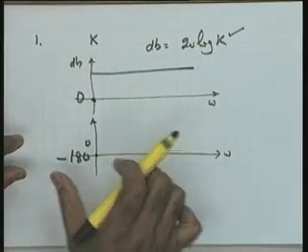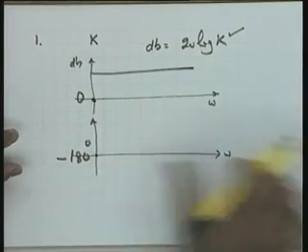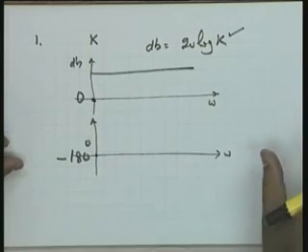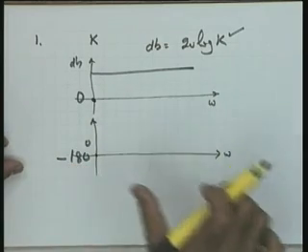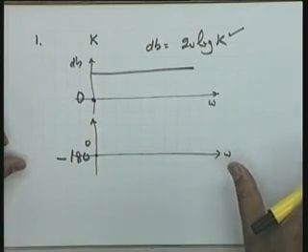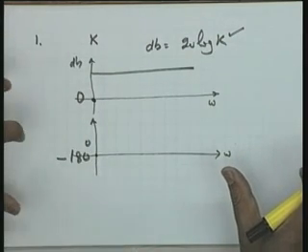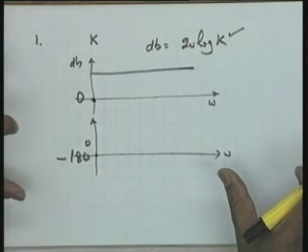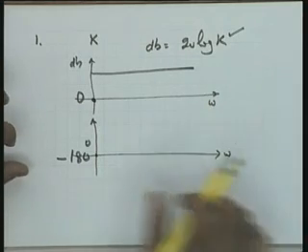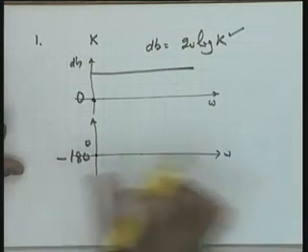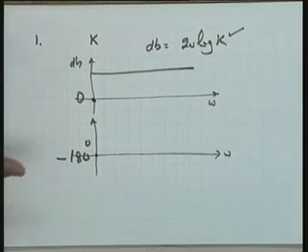So what will happen in the log scale, you see, the low frequency range because of the log operation will get elongated, and therefore you are able to effectively study the low frequency region as well as the high frequency region on a log scale. So this is an additional advantage of this log scale as far as control system study is concerned, because we are able to view the performance of the system over a wider range of frequency which is of interest to us.